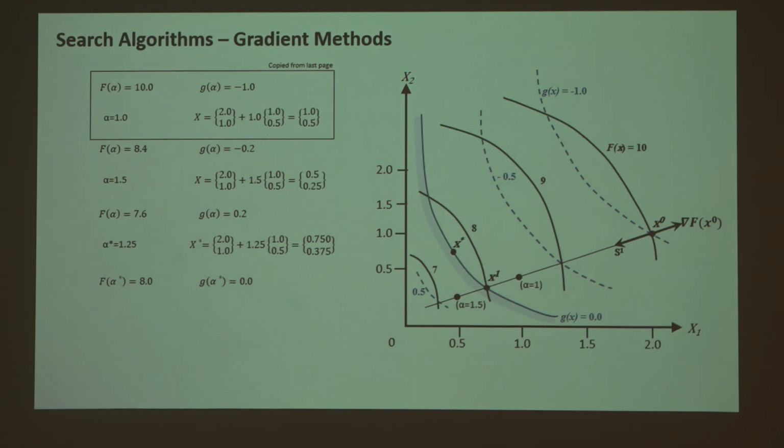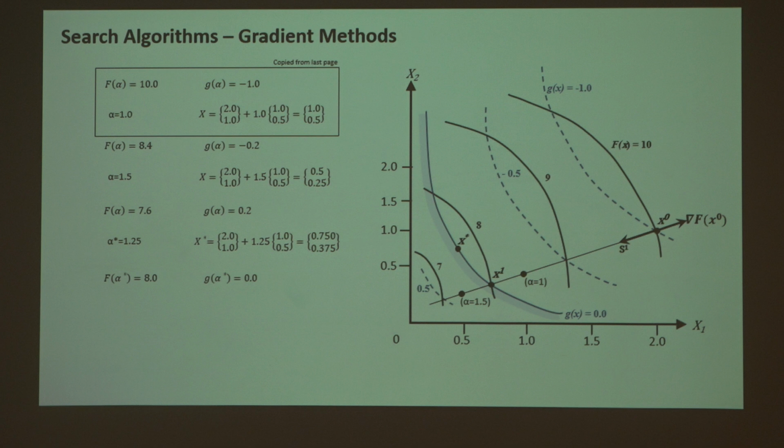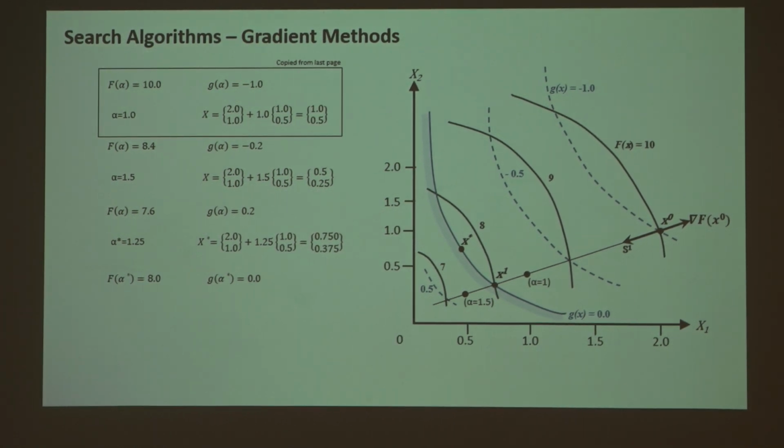Once you reach a point, do you just go all around that defined step size, just to make sure that's the local minimum? That is one way you can do it. The way this happens in the real world, and I'll show you this if I have time, but I might not, in real search algorithms is you start at multiple points. You pick multiple points in this design space, and then this algorithm will start doing this search direction, gradient calculation, search direction, step length for multiple points at once, and eventually they all begin to converge on one area. That's called the problem converging. So that answers your question, I'm sure.